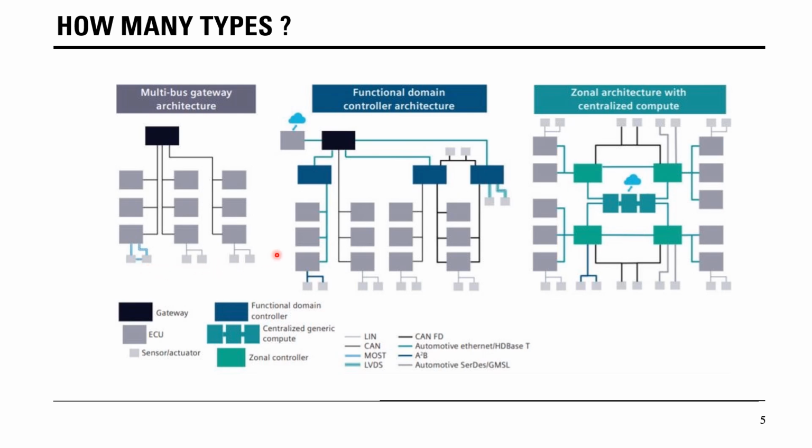And that's the reason there is a need to move to the functional domain controller architecture, as we see here, where we also have communication with the cloud outside of our car. We have a specific cloud that provides some features to the car, as well as software updates and so on, where the ECUs are connected together using different communication networks, not just CAN or CAN-FD.